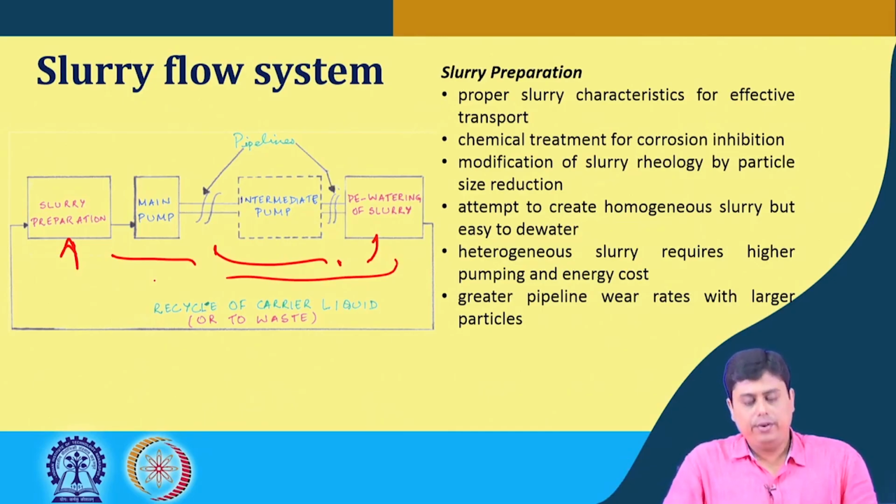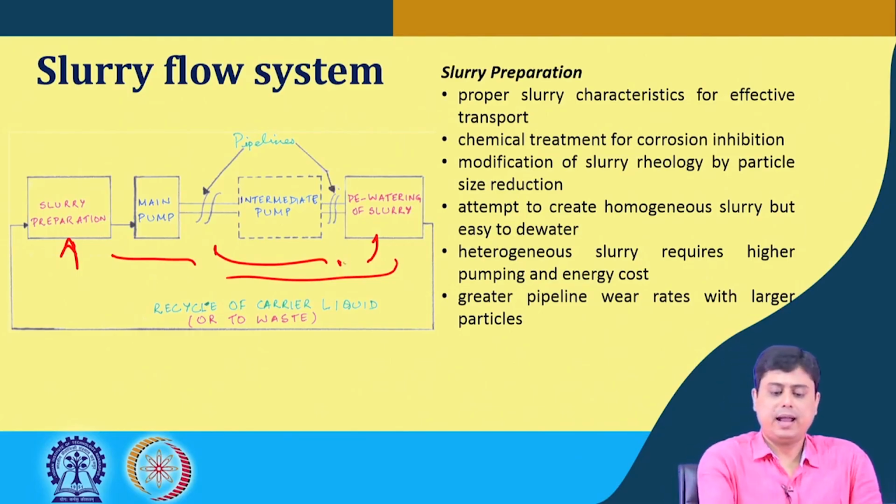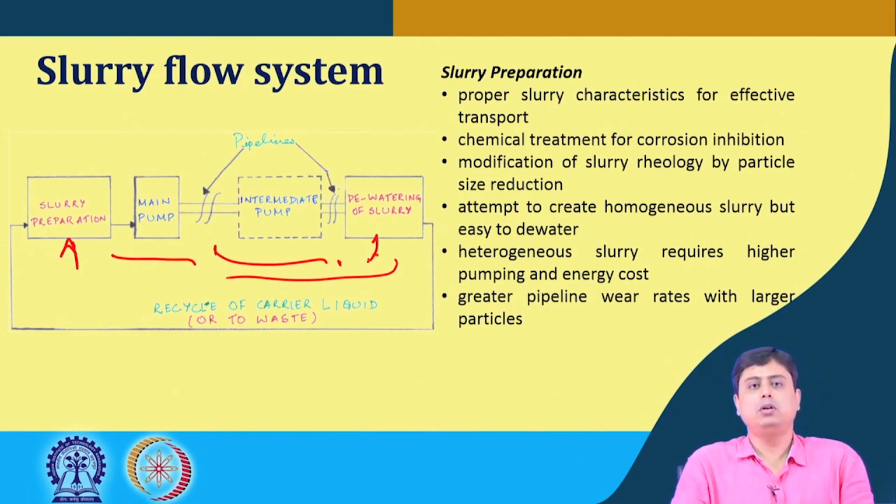So, every attempt should be made to create homogeneous slurry, but at the same time the particle size should not be so fine that the dewatering step becomes difficult, because essentially at this end we have to get the solids back.